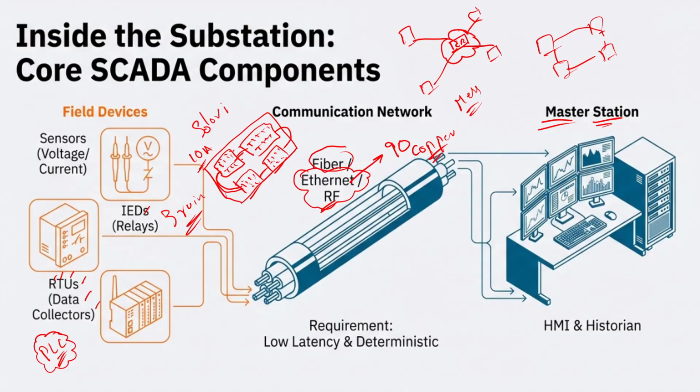So when we take this use case where the solar installation is spread across 10 acres, this has the limitation of 90 meters. We cannot use this. Instead, we can use fiber, where we have single mode fiber and multi-mode fiber. Single mode fiber goes up to 10 kilometers. The multi-mode has a limitation of 500 meters only, right?